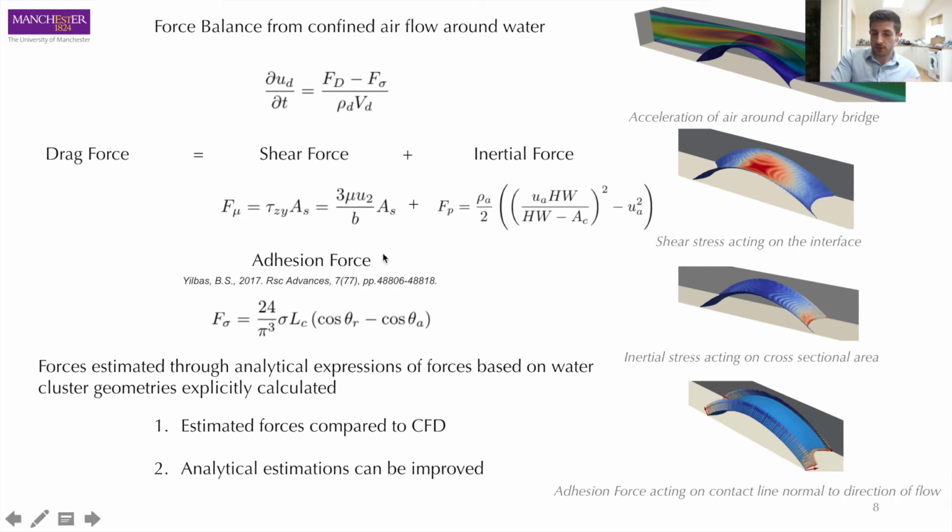We also have the adhesion force, which is related to the surface tension, and it's the capillary reaction which acts on the contact line normal to the direction of flow, and also incorporates the deformation in terms of the advancing and receding contact angles.